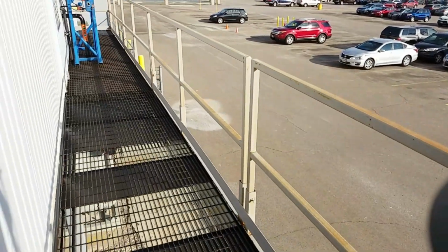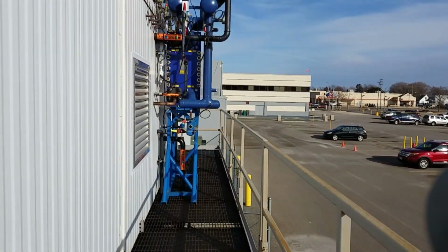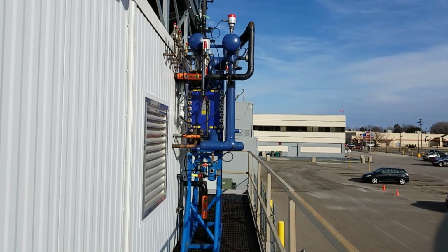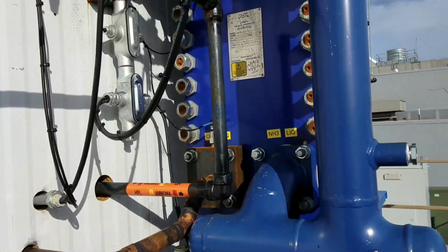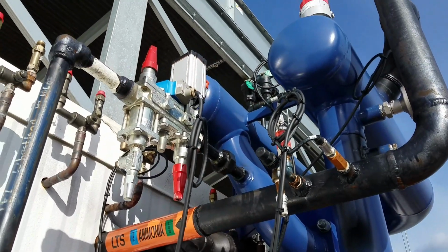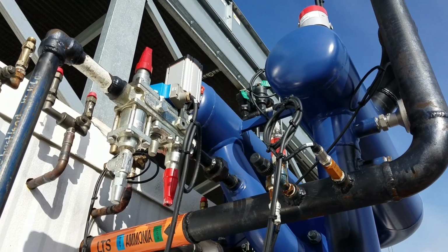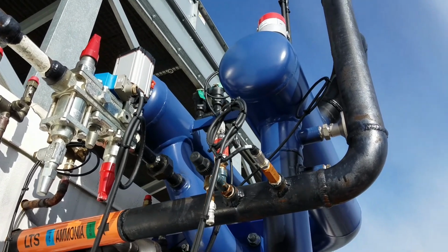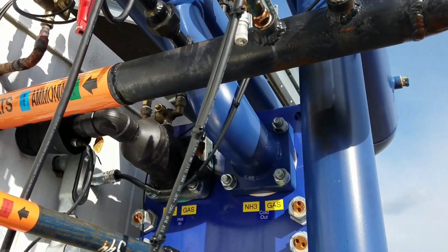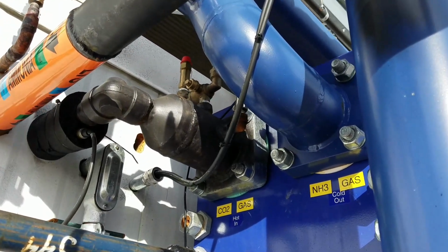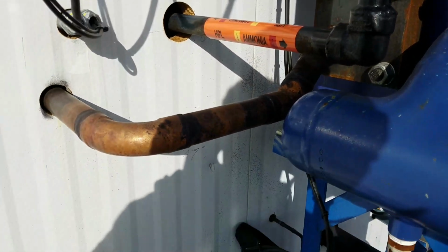As we walk out into the catwalk, we have our cascade heat exchanger outside. This is outside for testing purposes, for accessibility. Liquid is added to our heat exchanger in the same direction that the vapor is removed off of the heat exchanger. This helps desuperheat the suction gas that is returning to the compressor. Hot CO2 gas is sent into the heat exchanger and comes out condensed as liquid CO2.